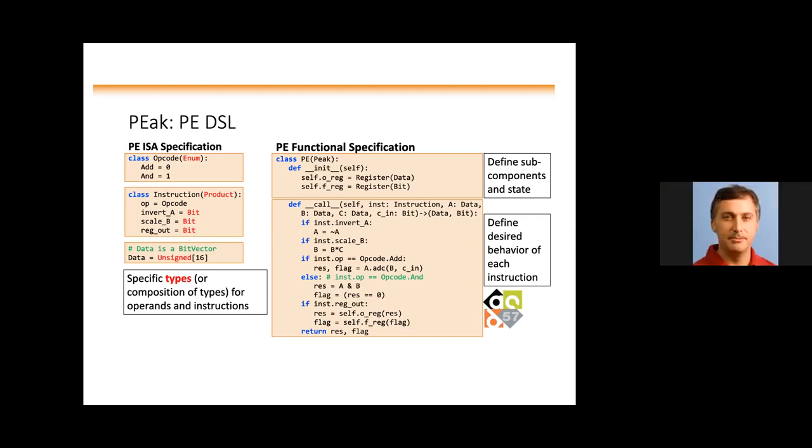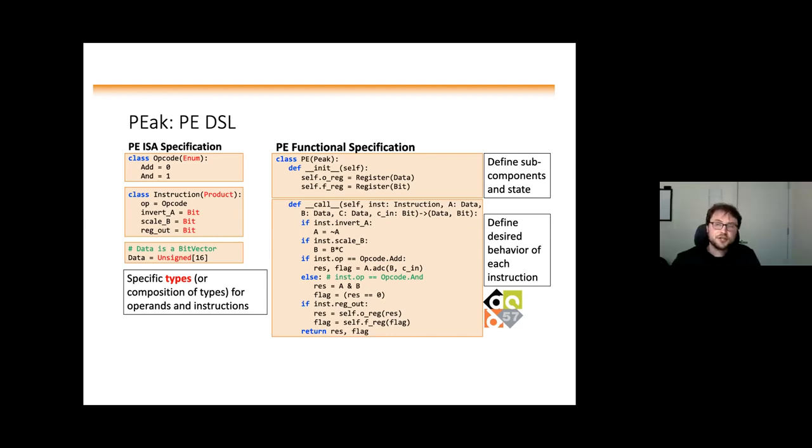It's curious because it looks very similar to PyRTL or PyMTL in some way. How do you distinguish with those ones? Or what's the difference? That's a good question. I think the differences will be immediately apparent on the next slide. I might be unknowledgeable about the real extent of what they can do. But one of the important things we get out of this is that not only can this be interpreted as RTL, it can also be interpreted as a functional model, and it can also be interpreted symbolically, so that we can get a pure symbolic expression for formal work for this specification. But I do agree that it might look similar to some of these other RTL design tools. In fact, this looks very similar to our Magma tool, which has the ability to specify things like this.